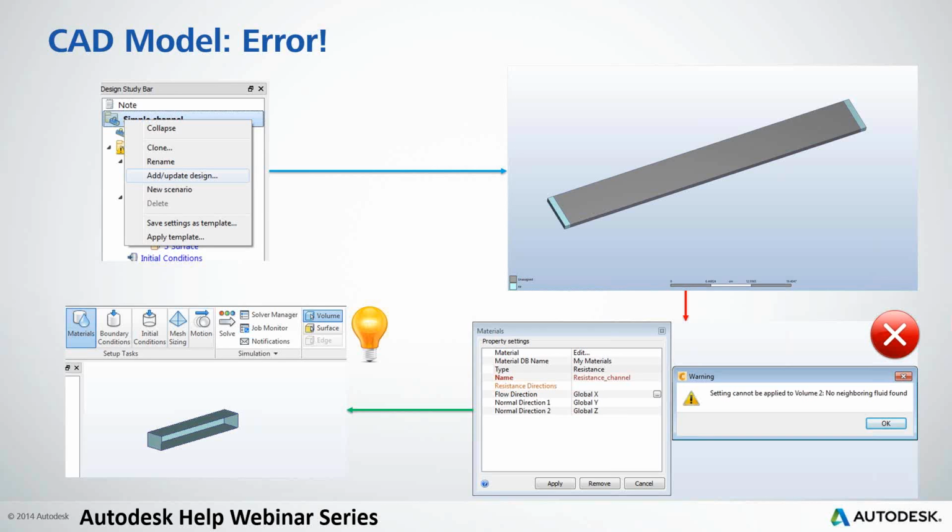And then I defined the air caps in here on the openings, inlet and outlet, and then I still have the middle part. I then edit the materials. I said edit materials, and then chose resistance, and then got the same error message.